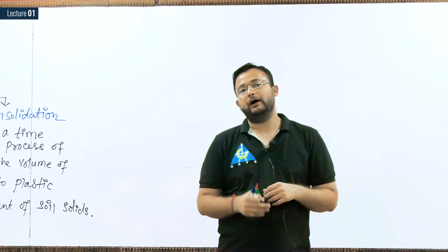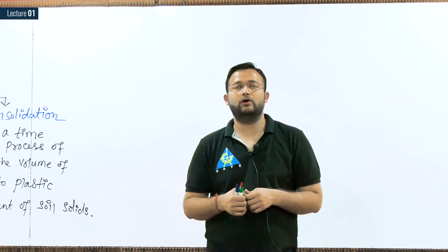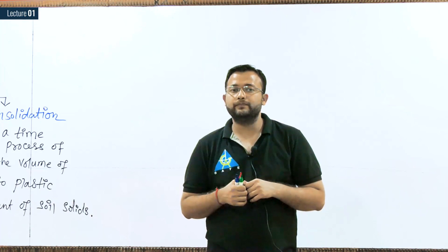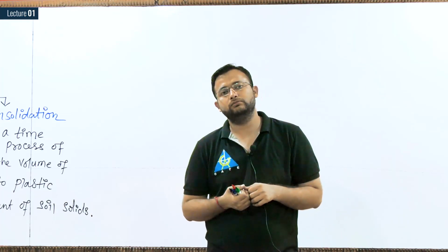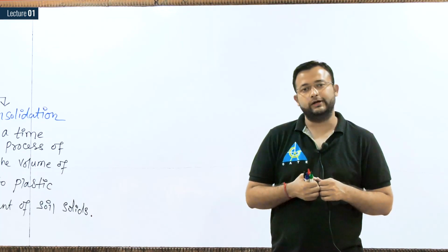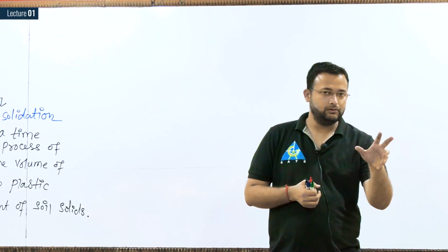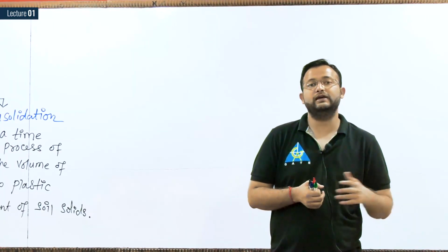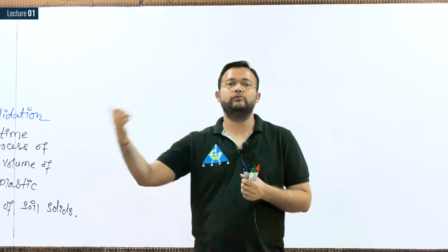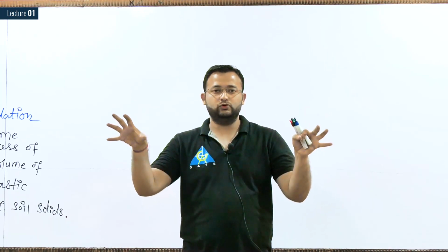Now, suppose all the voids of the soil are filled with water, then what will happen? You apply the load, and you are removing the water from the soil, the process we call consolidation. So in compaction we are going to remove the air from the soil, and in consolidation we are going to remove the water from the soil. So these two pictures are clear to me.